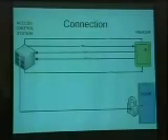So basically, this is what a standard reader would look like. You've got your positive and negative, which is dead handy because it gives me power. And then you've got the data 1 and data 0 lines, which are transmitting the actual Wiegand data. And quite often, you've got an LED, which is driven by the access control system, that basically goes green when you're allowed access.